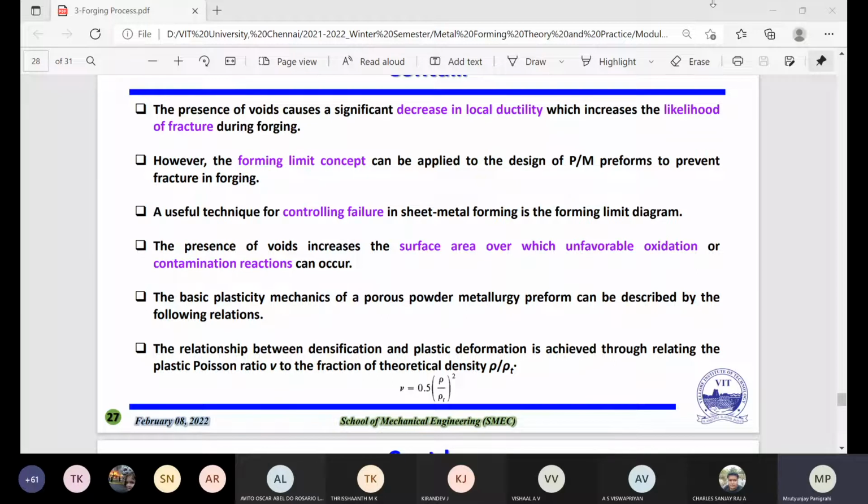I am not sure if it is available here in Chennai, but in Vellore we have that equipment, BET analysis. You put your sample in a glass, like a small cylinder or maybe a bigger kind of structure. You put your sample, maybe around 5 to 10 gram. Then after 1 or 2 hours, you will find the porosity of that powder sample. So these are the new techniques we have nowadays.